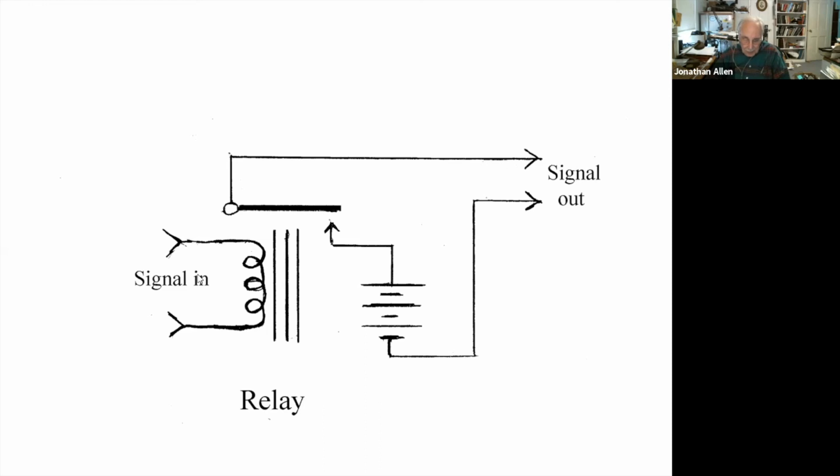The first challenge was high vacuum. Arnold, and especially Langmuir, realized that residual gas was not only unnecessary for electron flow, but was in fact bad. Both teams exploited the advances in vacuum pumps to get a hard vacuum in the range of 10 to the minus 6 or 10 to the minus 7 torr.